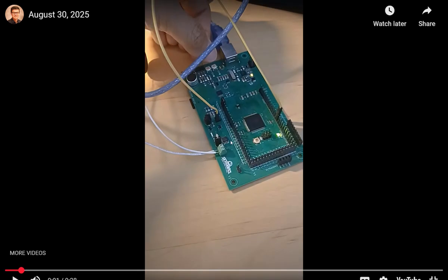Still the same task. No. I think it's this guy. So you have to put a jumper here. This is for the IR. This doesn't have to be on. I don't usually do this, because just in case it's emitting IR, it couldn't see, it's getting super strong because it's running a lot of current. You want to disconnect this. But I think it's this guy. Okay? This jumper needs to be shorted.